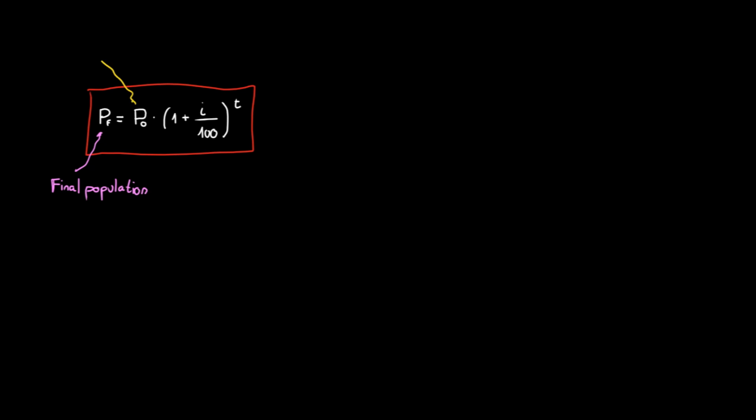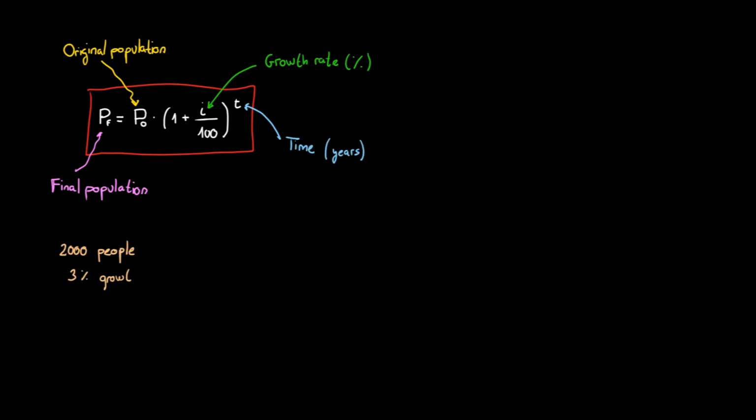This is the geometric formula, one of the most widely used forecasting methods, especially for rural and smaller systems. The formula compounds the incremental growths. For example, for a population of 2,000 over 30 years growing at 3%, it renders almost 5,000 people.